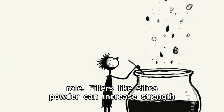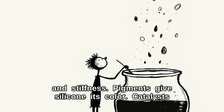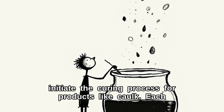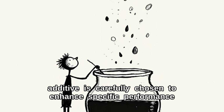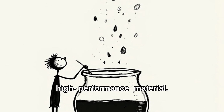Building on that, various additives also play a huge role. Fillers like silica powder can increase strength and stiffness. Pigments give silicone its color. Catalysts initiate the curing process for products like caulk. Each additive is carefully chosen to enhance specific performance characteristics, turning the basic silicone polymer into a high-performance material.